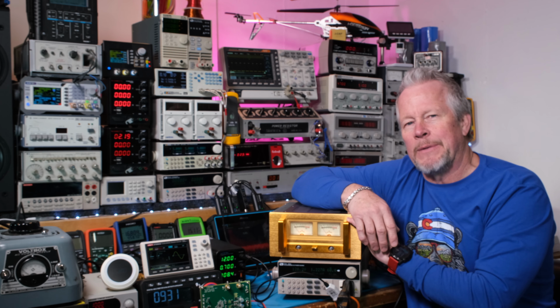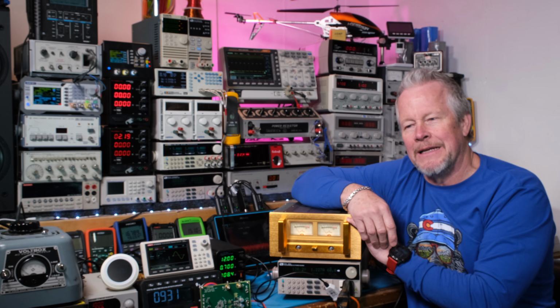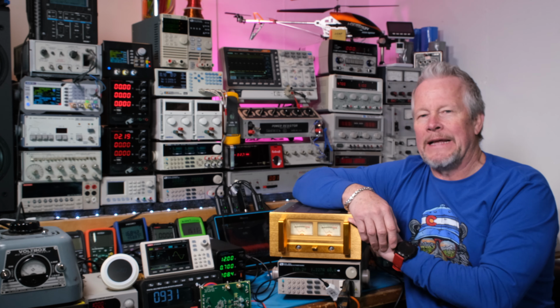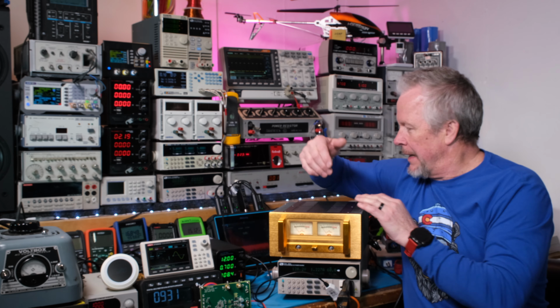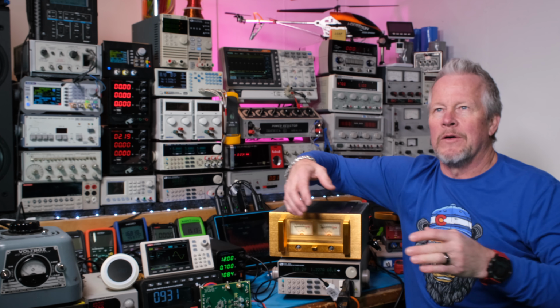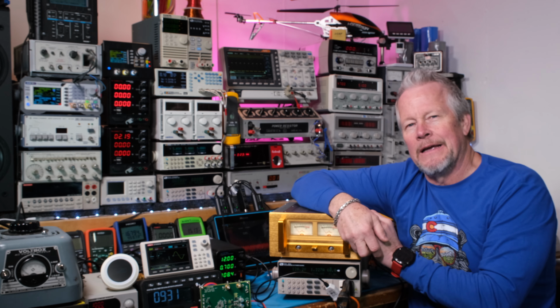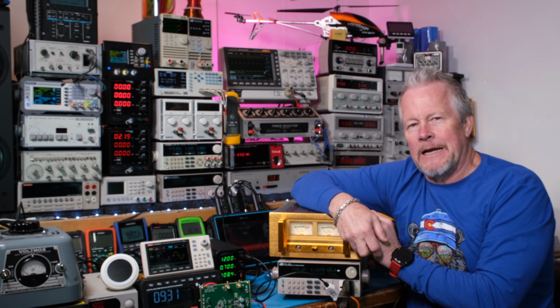In an unregulated power supply, with a big old bulk capacitor, that thing will dip all over the place. You need more, bigger capacitors to try to hold it level, and that's what's happening in the audio world. Oh man, the bigger capacitors you can get, the more of them and the bigger of them, oh, that's the way to go. Well, that's because they're chasing their tail, and they don't really know how to design power supplies.